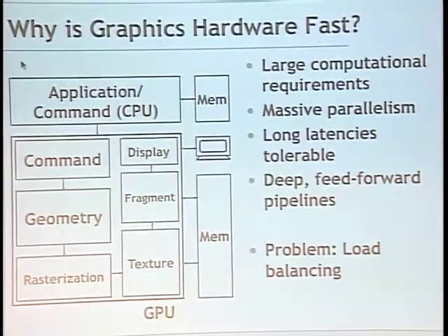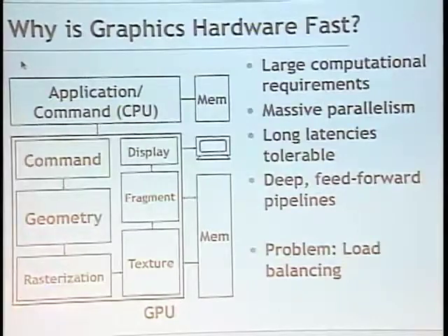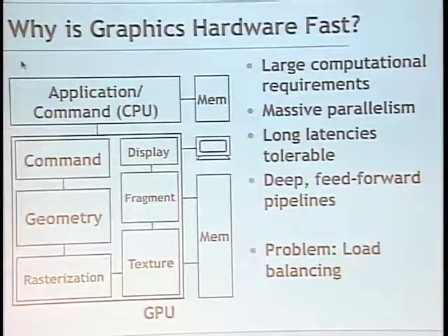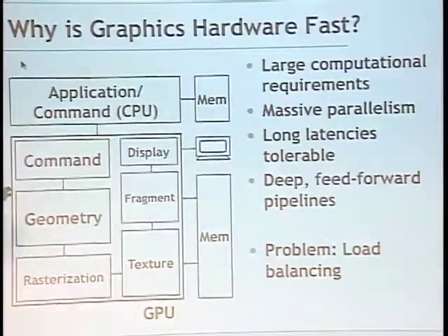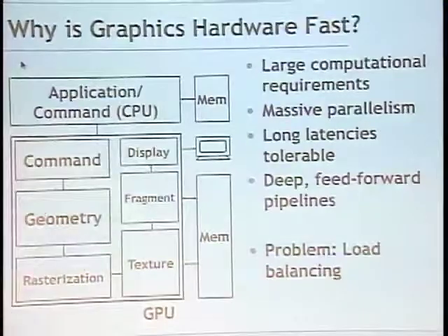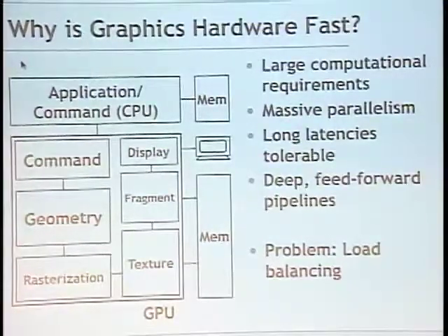So this is why people have historically built graphics processors in this way. Okay? All this stuff, plus the fact that you can customize this to do its particular task. This is the way they felt they could throw the most computation on the chip and keep it busy. It's not just having a lot of computation, it's being able to keep it fed. And this is a structure with very simple control structures and these deep pipelines with lots of latency tolerance that's well suited for keeping it fed.